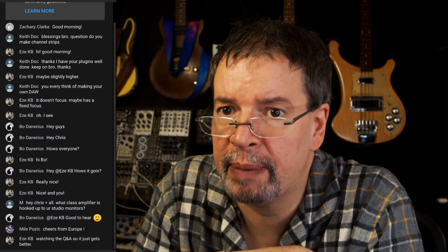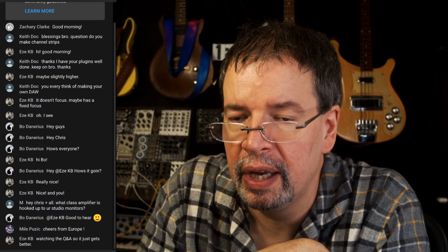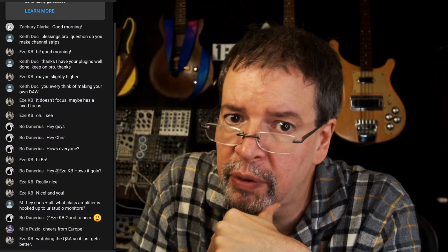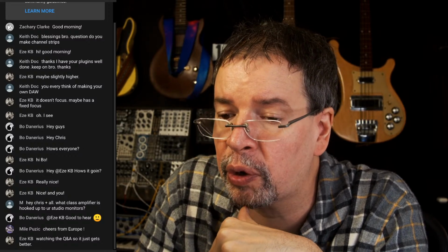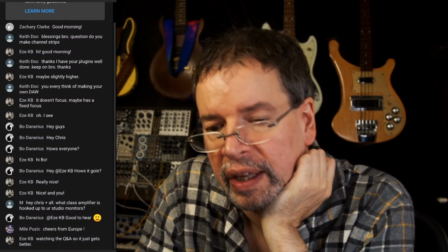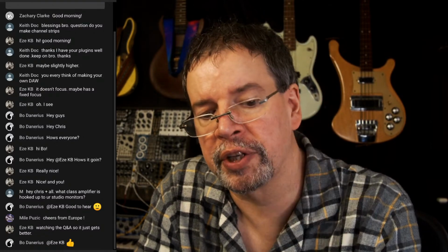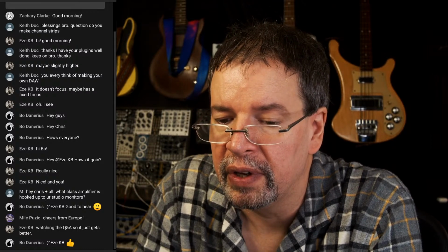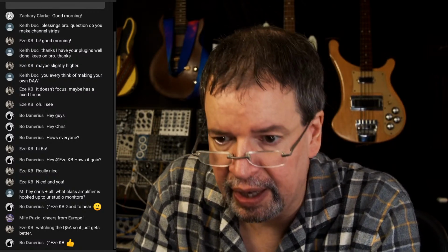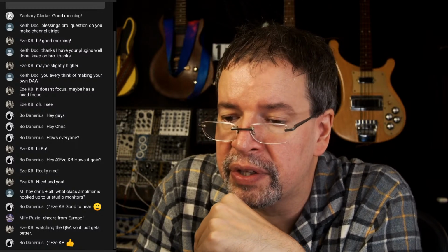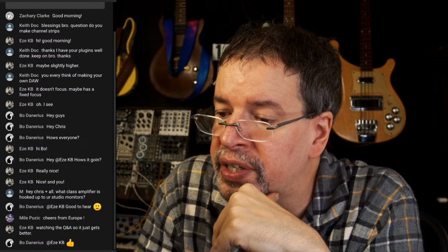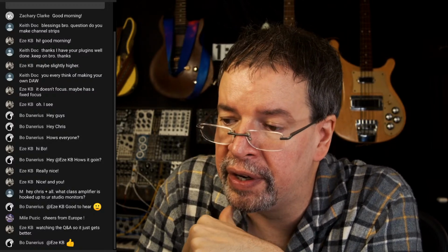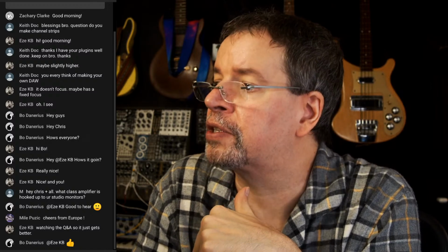Emma has a question. What class amplifier is hooked up to my studio monitors? That is a Channel Islands D100. It's kind of a fancy pants amplifier, but it's a class that is really quite accessible these days. In fact, it's possible to build some of these things yourself, DIY. It's a Class D amplifier. And the deal with the Class D is it's like a kind of digital amplifier, but it's more like SACD or DSD, direct stream digital, rather than CD or PCM digital.